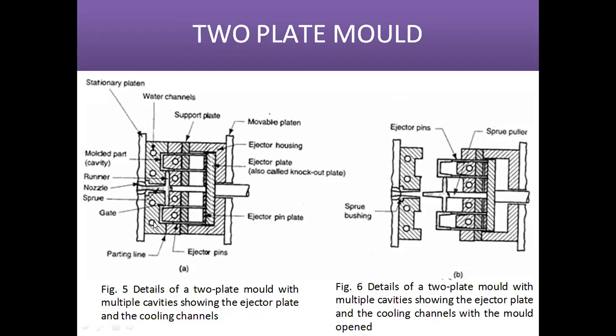To eliminate that air from the plastic melt during the solidification, some air vent must be at the parting surface of the mold. This is the parting surface. So at the parting surface of the mold, there should be some air vents, and the size of the air vents is around 0.03 mm deep and 12 to 25 mm wide.